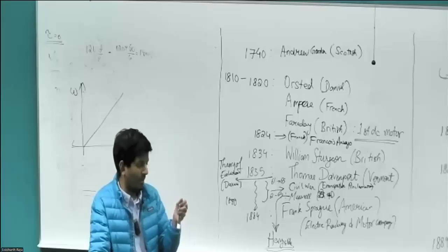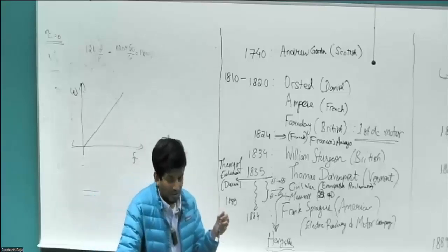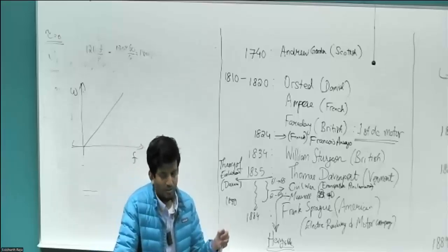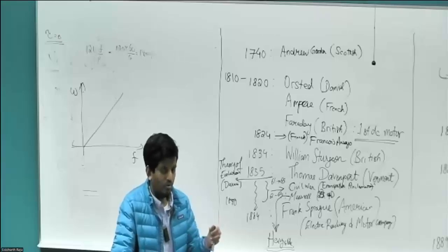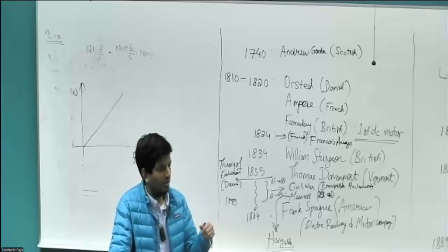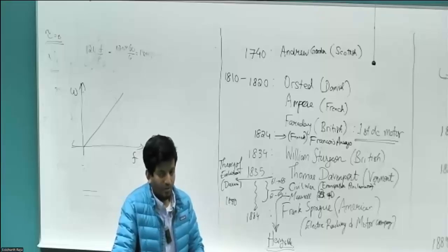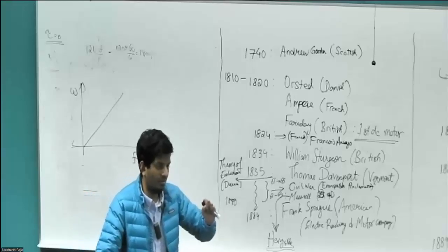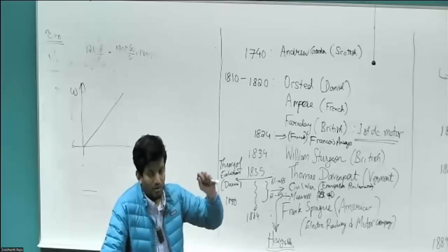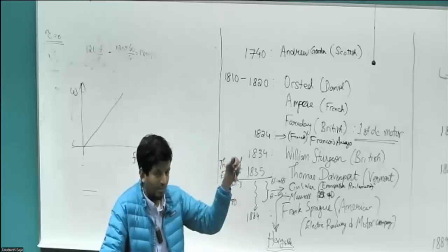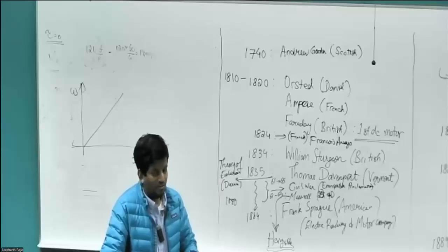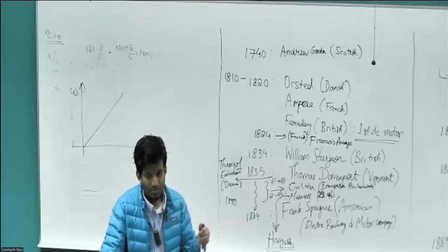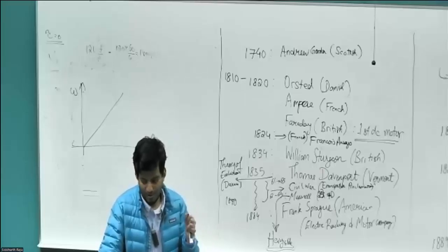So in the past, permanent magnet synchronous motors did exist, but they used to have a whole bunch of resistor networks connected in series to handle all this inrush current, to bring it slowly into synchronization and so forth. It was a big hassle. Compare that to induction motor, you can directly connect it to the grid and it will start spinning without any problems, right? So that was the reason that permanent magnet motors typically stayed within the auspices of generators alone. On the grid side, generation is always permanent magnet generators. But when it came to load, particularly industrial loads, induction motor became the most prominent motor because it's extremely robust, right?